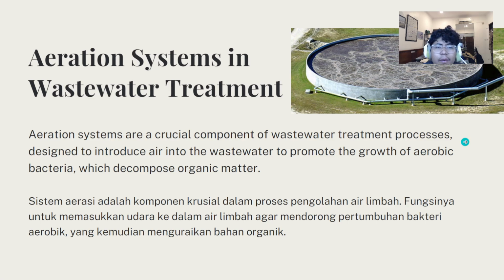So what are aeration systems specifically? Aeration systems are a crucial component of wastewater treatment processes, which are designed to introduce air into the wastewater to promote the growth of aerobic bacteria, which decompose organic matter. To treat the water, oxygen needs to be there, air needs to be there, so that organic matter will decompose faster. In this sense, a circular economy would be to reduce the footprint of the wastewater treatment.